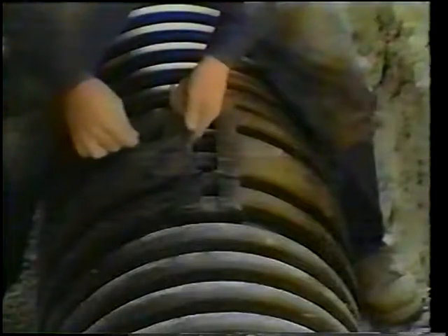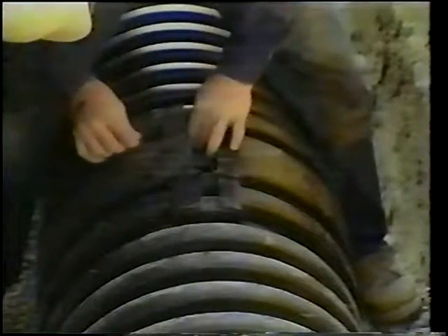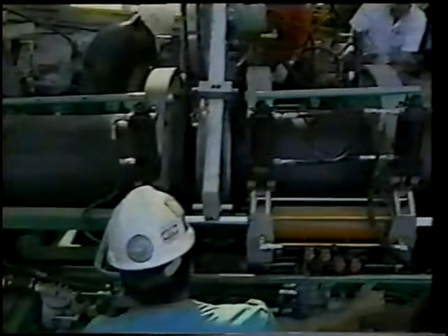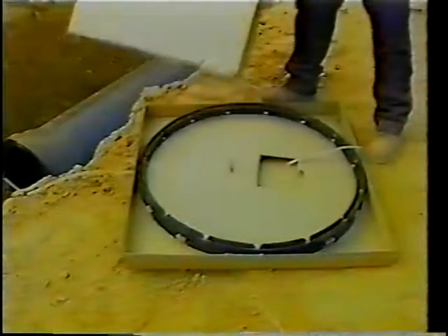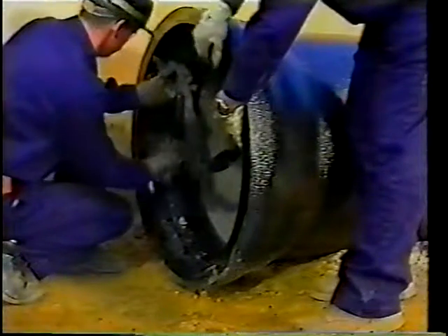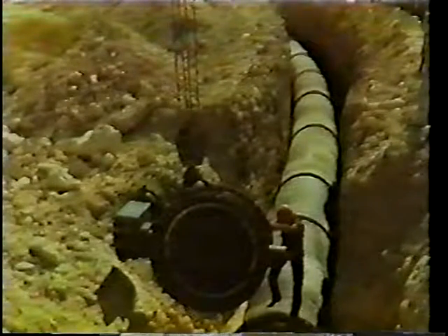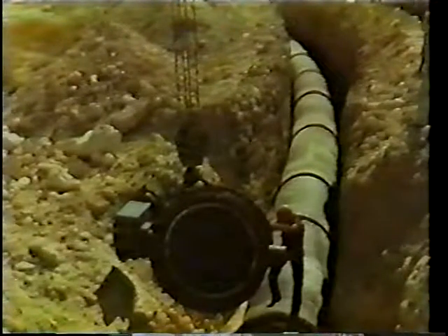Joining methods for corrugated PE pipe include bell and spigot joints, coupling bands, and wire ties. Lengths of solid wall PE pipe are usually trimmed and butt fusion joined on site. Push-on joints are also used for ductile iron pipe. Variously configured gaskets can be placed in the socket restraining groove of the bell. Gasketed bell and spigot joints are flexible enough to allow longitudinal deflection of the pipeline.